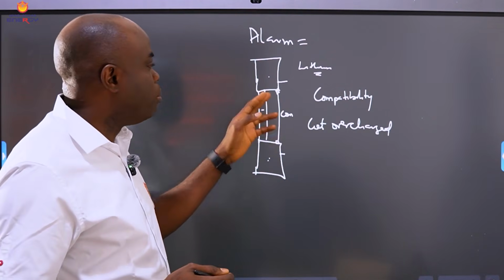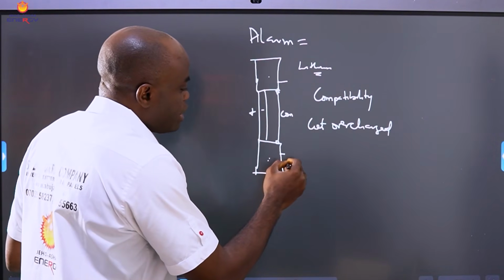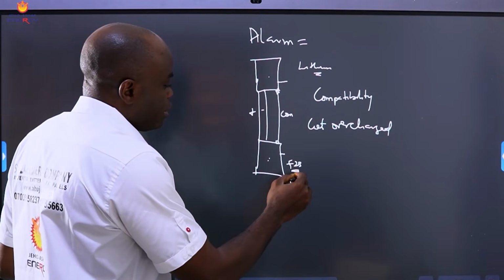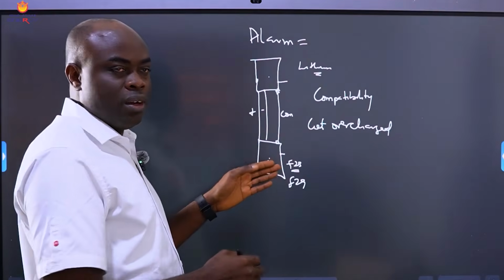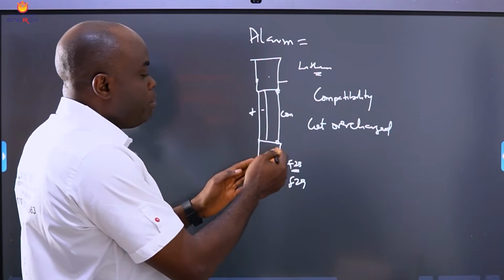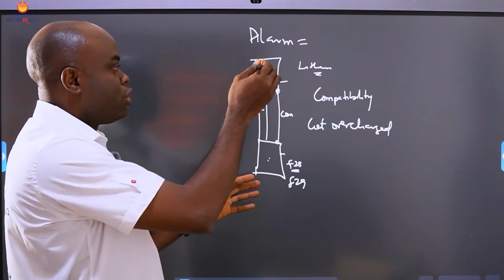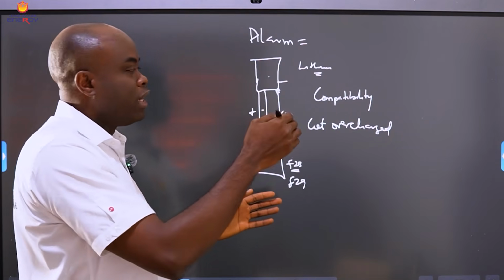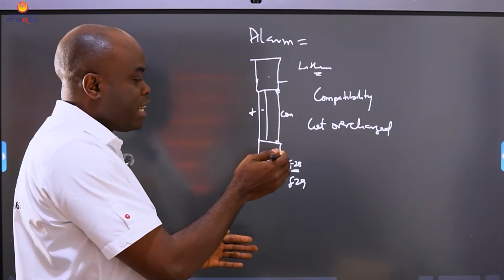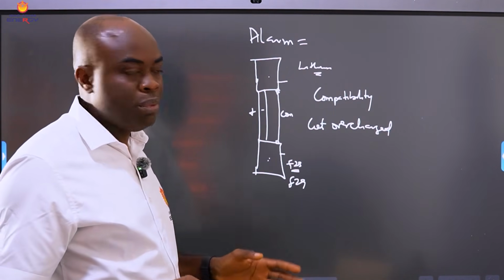Benefit of your communication cable. But if this battery has a fault, it's showing an error. Let's say F23, or maybe there's an error F29 on its screen, but the inverter keeps on discharging the battery. But most of the time, the BMS in this battery will cut off supply on its own, and it will draw the attention of the installer or the owner that my inverter is not supplying power. Why? When you come closer, you see that the battery is giving an alarm, right? That is just the benefit of BMS.